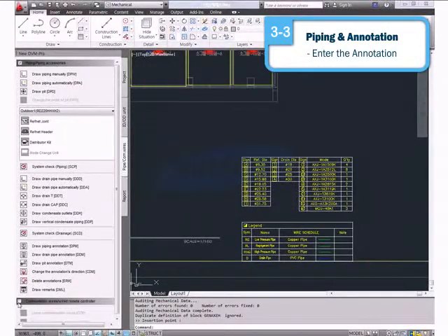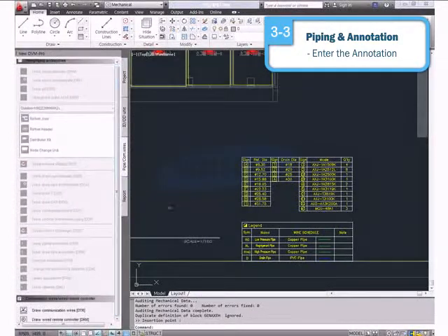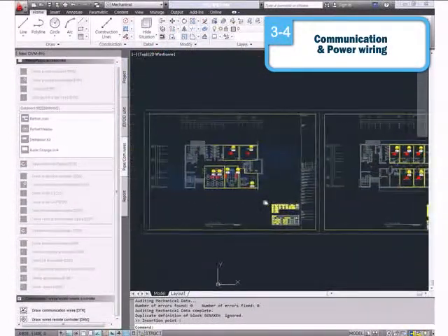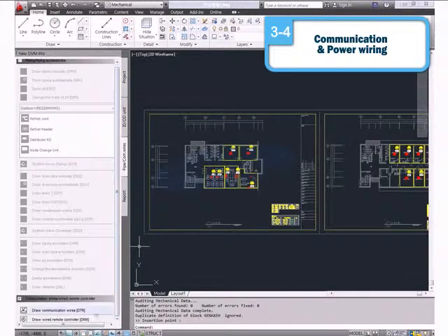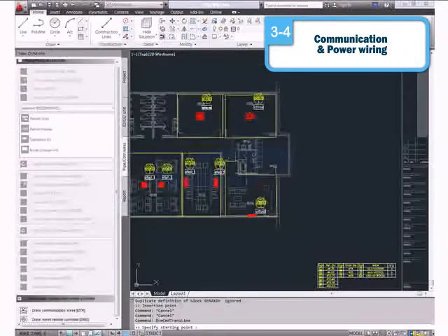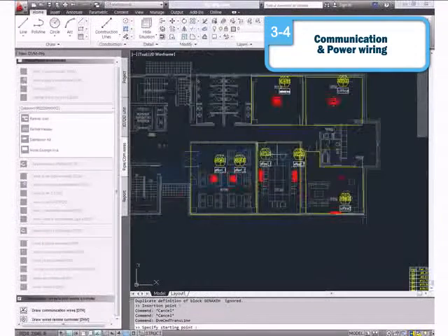When you reach the communication wire and remote wire step, all the pipe drawing will disappear. For the communication wire, you may click the Draw Communication Wire icon to connect the indoor unit pit and the outdoor unit. If you move the cursor near the indoor unit, the connection point will be created automatically.